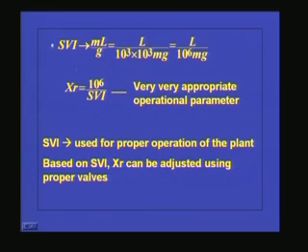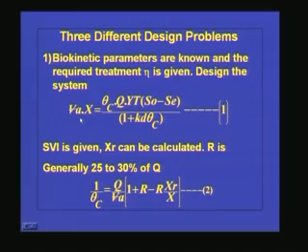So in most cases, this SVI is used for proper operation of the plant. Based upon the SVI, we can calculate XR, and this XR and the biomass concentration in the aeration tank can be adjusted using proper valves. So this SVI is very, very important.